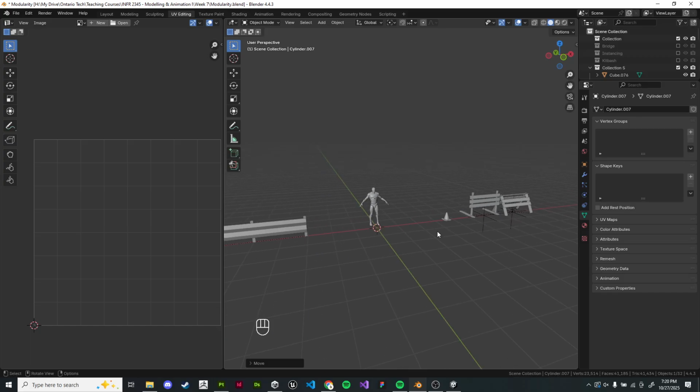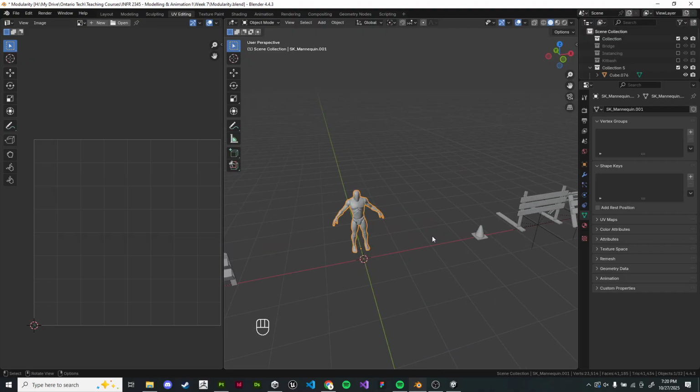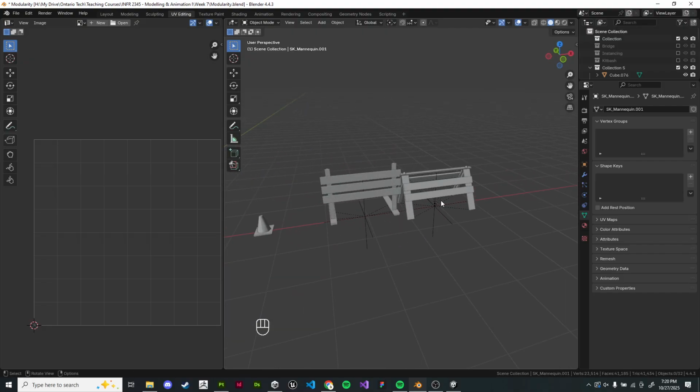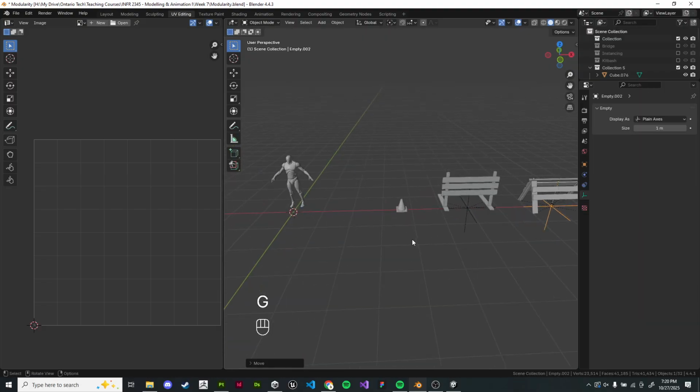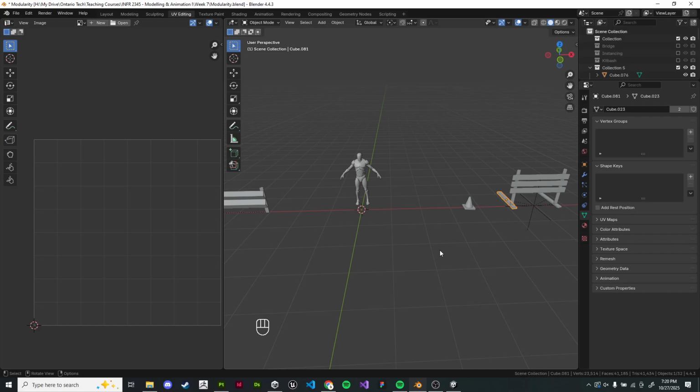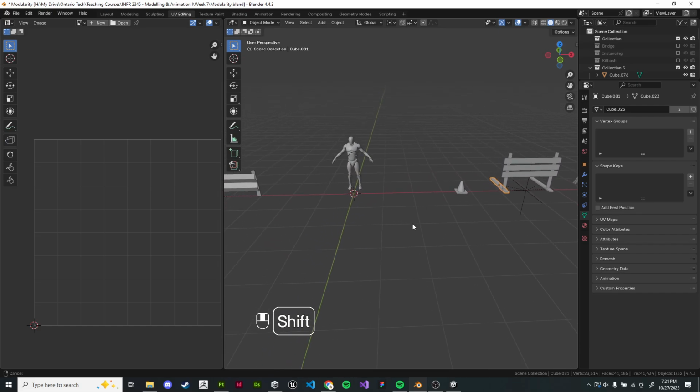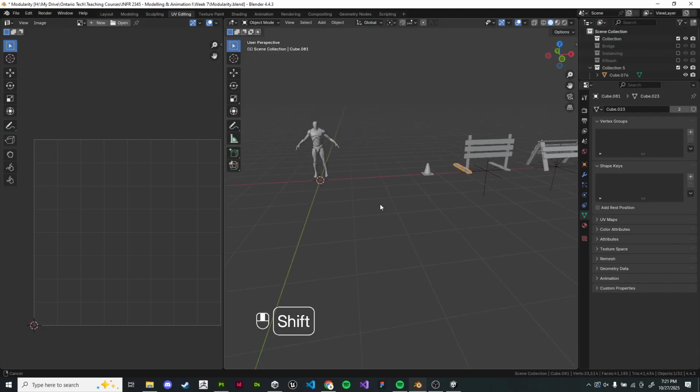If I wanted to make that billboard, I wouldn't have to model any new pieces. I would just make use of all of the existing pieces I've got and then go from there. I'll do that quickly as a last example, right? We don't have to make any new pieces, so we don't have to worry about our UVs being messed up by adding new models, just about adding places where we need new textures.